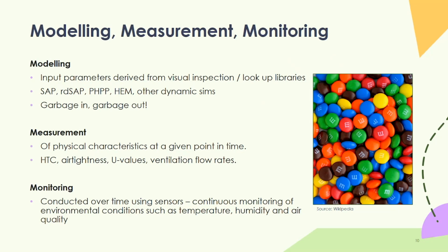We're speculating as to the level of thermal bridging. We're doing the best we can with modeling of thermal bridging, but actually it's still just a model and a prediction. And so all of these assumptions stand to compound and present quite high levels of uncertainty overall in the modelling of our buildings. So modelling in isolation has its risks.